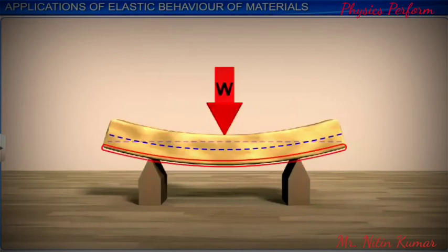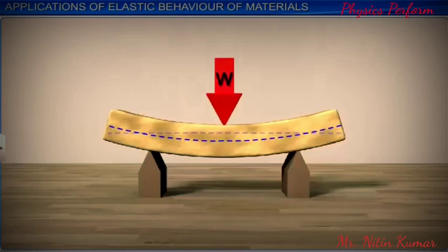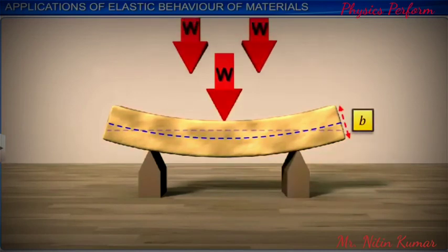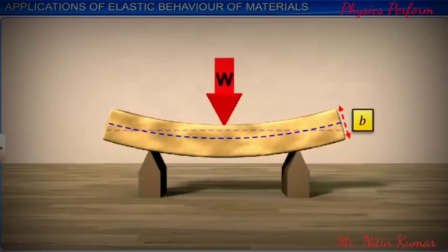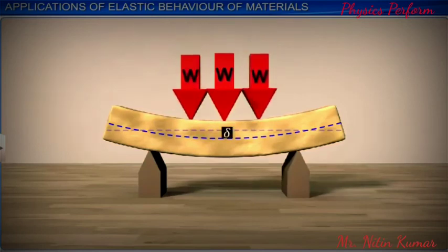The deflection of the beam at the midpoint is its vertical deflection compared to its unstretched position. The greater the width B of the beam, the greater the maximum load the beam can support. The deflection delta at the midpoint can be determined experimentally as well as theoretically calculated. As the calculation involves high-level mathematics, we avoid the derivation of the expression in our context.